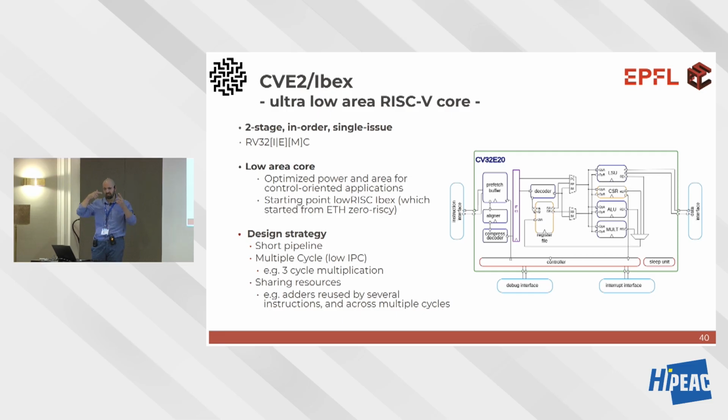Plus, you need a state machine, you need states to know whether the first 2 bits are the last 16 of the previous instruction, so they are not bits 0 and 1, they are bits 16 and 17 of the previous instruction. Like UTF-8, the Unicode encoding. I don't know the specific encoding, but you need a state, yes. You need to remember what you fetched before.